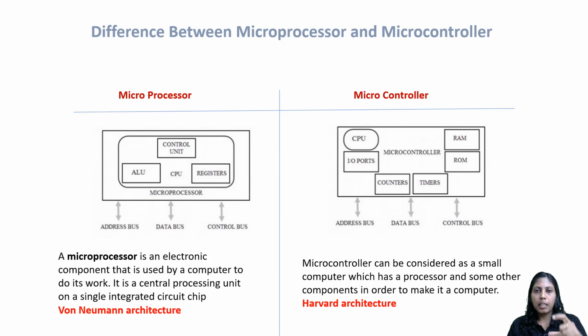After that, the data bus will be enabled, and through that data bus I will be receiving some data. But before that, I have to enable the control bus. In the control bus I will give the signal, whether I want to read from that location or write to that location. So in the control bus we'll be sending the control for a reading or writing operation. At a time I can choose only one, right? If I send a read signal through the control bus, I will be able to read from the location, the address which I passed to the address bus, from that memory location. Similarly, you can do write operations also. So that's about the buses.